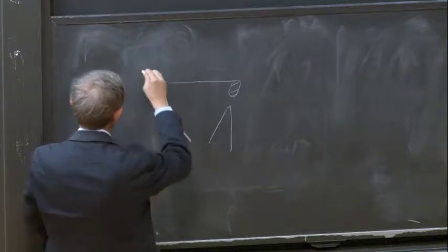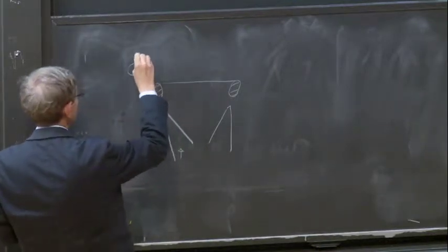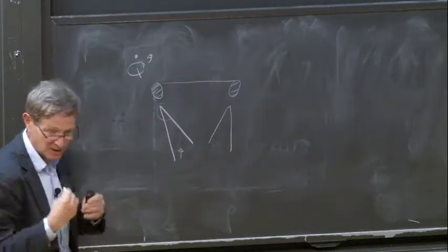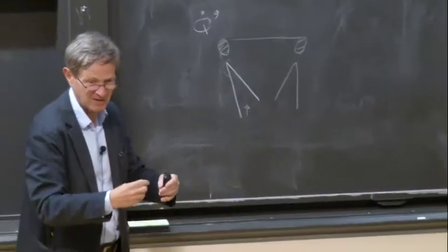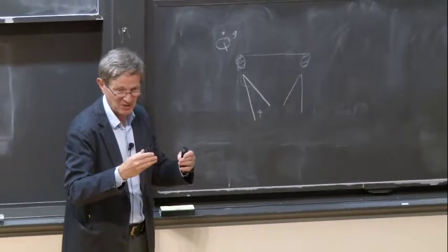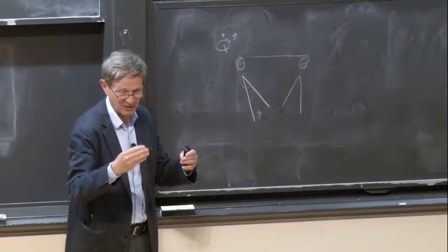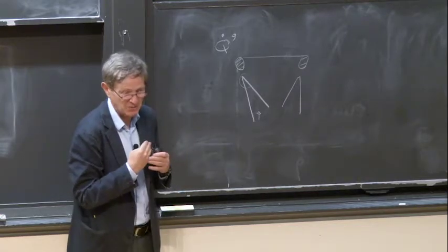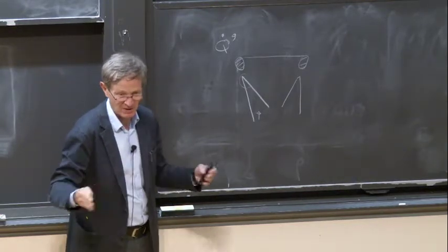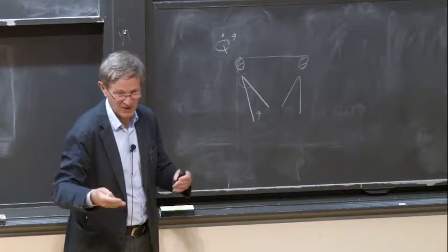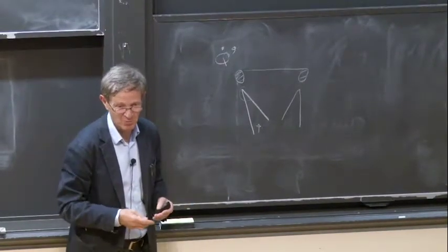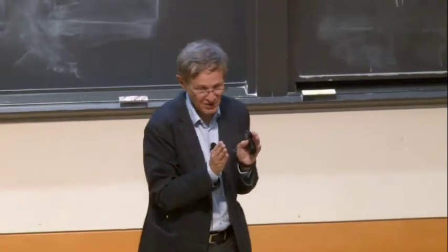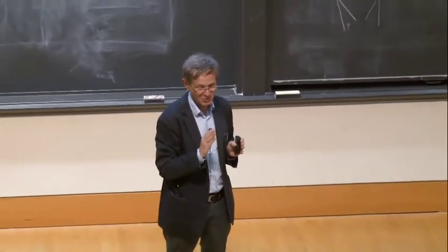And this will produce a sudden pulse of heat release. It will produce a pulse of heat release at a later point. So you isolate a torus of unburnt reactants, and it burns. And so there is a rapid destruction of reactants, and this gives a pulse. And so this M flame, because of its geometry, is able to produce that.